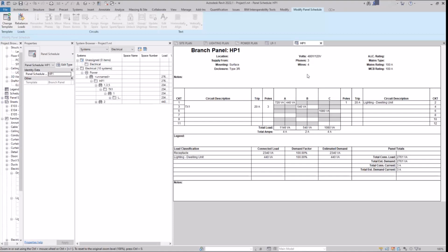So it's like, okay, do we have to do this? No. Does it make sense from a practical standpoint? Yeah, let's go and break it up. So we did 4 or 5 different breakers. They were very lightly loaded. But if something trips because a rat got into a light switch, the whole level is not going down. So does that answer your question? Yes. Okay, cool.